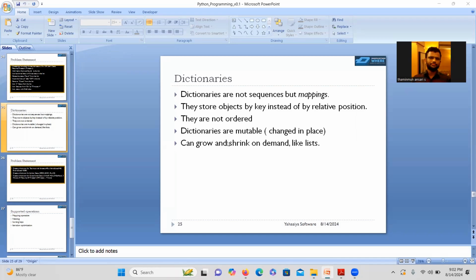In a CAN database, we have CAN signals, and the CAN signals are associated with a numerical value. So these CAN signals that we use inside the simulations are just like a symbol or key. Actually, in the packet we are only transmitting numbers. So the packet is going to contain only numbers, but when we represent them in the simulation, for our understanding, we link them with a key. Key means we link them with the definition of the signals that we have in the CAN database.